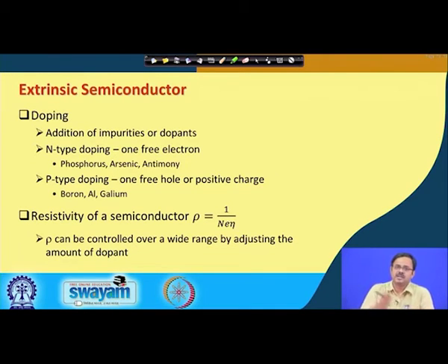Okay. Compare that to N-type, group 5 elements, 5 electrons on the outer shell. Combine that with 4, so that makes it 9. So, 8 of them are in the outer shell, and then there is one that is free, that is a free charge carrier.